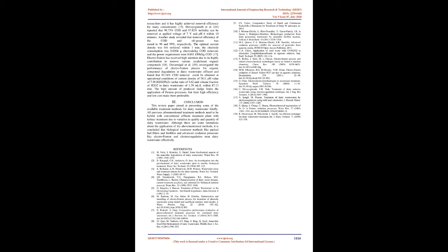The key limitation of biological treatment methods is the formed sludge, especially during the aerobic biodegradation processes, which may cause serious and costly disposal problems. B. Advanced oxidation processes, AOPs. Advanced oxidation processes prove to be promising methods in destruction of most organic and inorganic matters by converting them into benign end products such as CO2 and H2O. Many researchers frequently employ AOPs since they provide many potential processes for hydroxyl radical production, which are one of the most powerful oxidants able to oxidize many organic compounds to CO2 and H2O and inorganic ions.